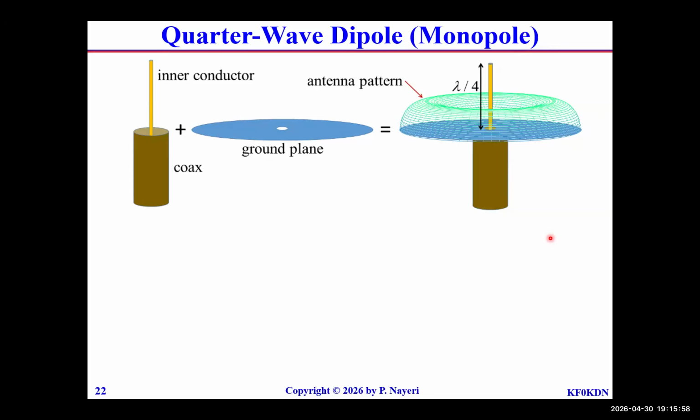Now, one question, and this is something we're not going to discuss a lot, but you can imagine operating at much lower frequencies, for example, HF type of frequencies. The antenna size becomes prohibitively large. So the question is, well, can't I have a shorter wire and would it work? The answer is yes, but there's an issue with that.